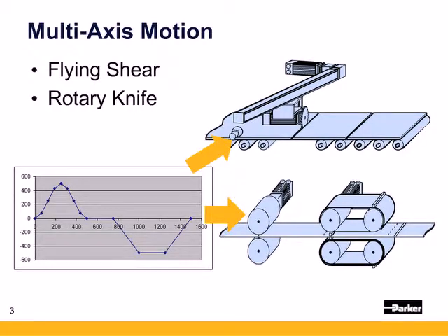In terms of the cam profile, this is stored as an array with the ACR9000 controllers. So each part of the machine or each master could be following that cam profile. Optionally, you could run these two parts separate from one another, or you could synchronize the masters with the sync command.